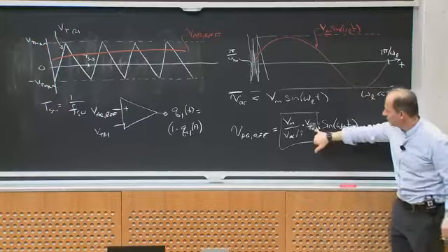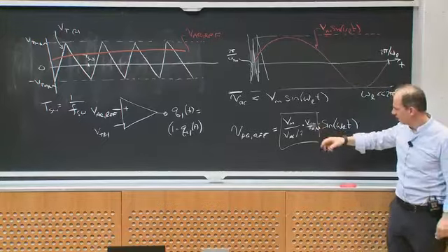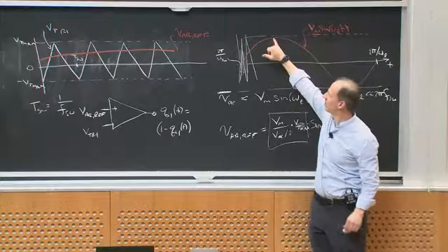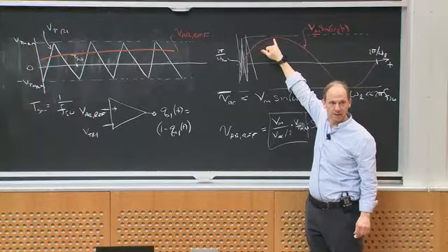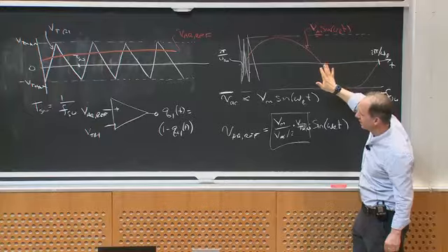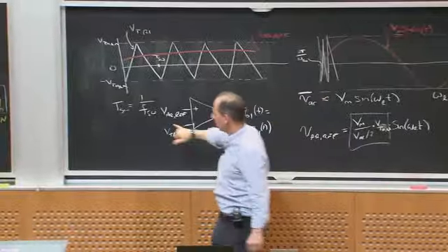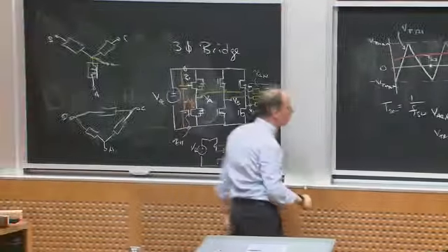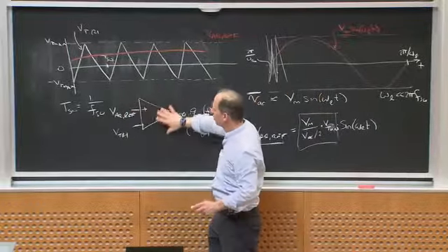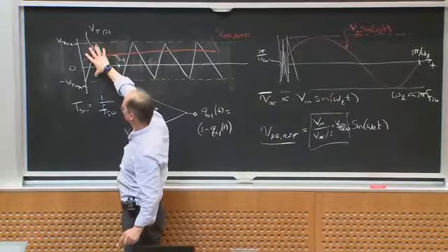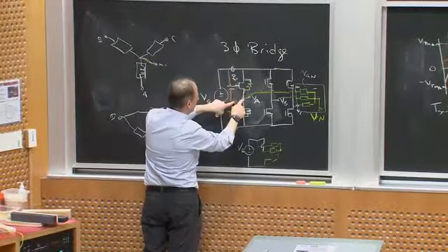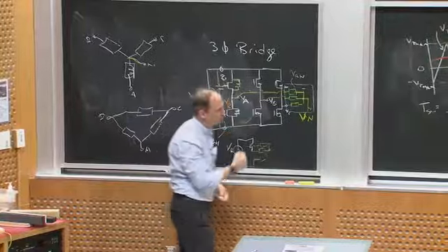Right? So if VT max was 1 volt, just for simplicity, I'm going to make V sub m over VDC over 2 the height of my reference waveform. Okay? So if I do this, then what I'm going to get is a VA as a result of running this into this comparator network, right? Because this is my triangle wave for my controller. The peak of my voltage is switching between plus VDC over 2 and minus VDC over 2, right?